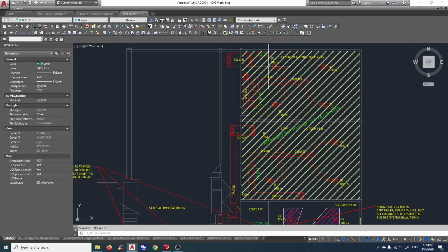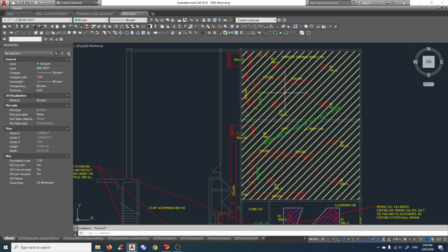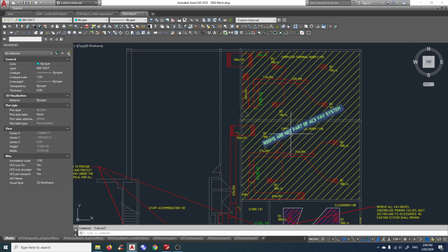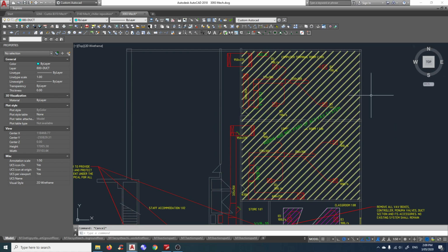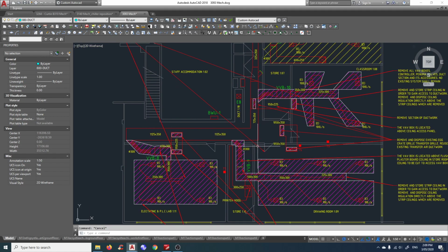It's not served by chilled water. It's served by a normal DX system. These 2 rooms are not part of AC3 anymore. They've decided to take them out from the chilled water because at one point they run classes on Saturday. There's no point running the chiller that is capable of running the whole block F just to cool down 2 rooms, which just makes sense. And this is the room in the corner, and there's a stair to go down to the toilet if you remember.